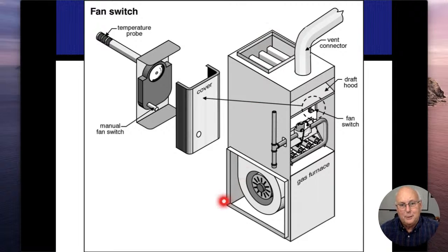So when I'm talking about a 30 to 60 degree temperature rise, if we come in here at 70, this is where my heat exchanger is going to be. That's where I'm going to add heat to it. And then above the heat exchanger in my plenum, that's where I want to be at that 100 to 130 degree mark.